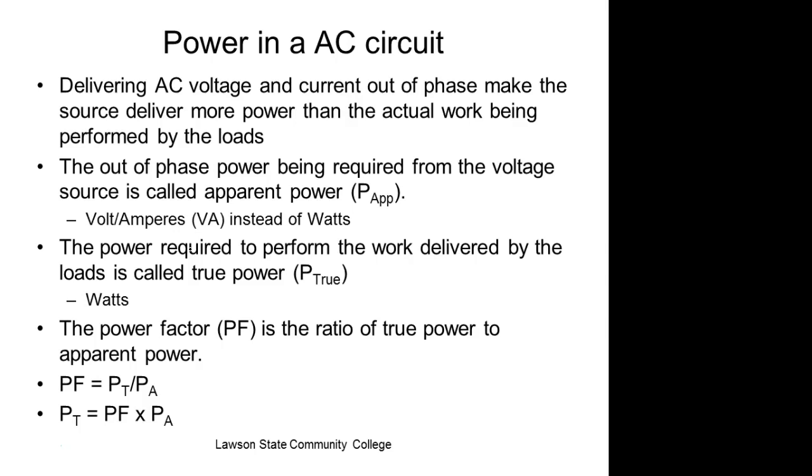So capacitors basically eliminate what inductors do. Our power grid is predominantly inductive, because all your transformers are inductors, all your motors are inductors. So we call it power factor correction. And this is going to be on the faceplate of your motors.